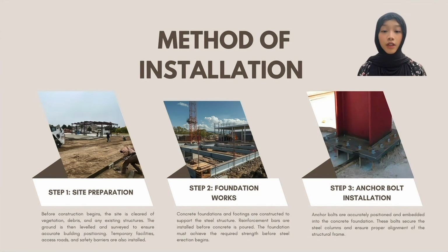Step 2. Foundation works. Concrete foundations and footings are constructed to support the steel structure. Reinforcement bars are installed before concrete is poured. The foundation must achieve the required strength before steel erection begins.